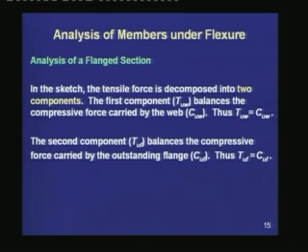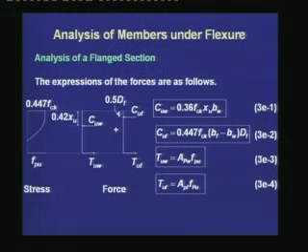The second component, TUF, balances the compressive force carried by the outstanding flange, which is CUF. And here we have the second equation, which is TUF is equal to CUF. Next, we are writing the equations based on the principles of mechanics.